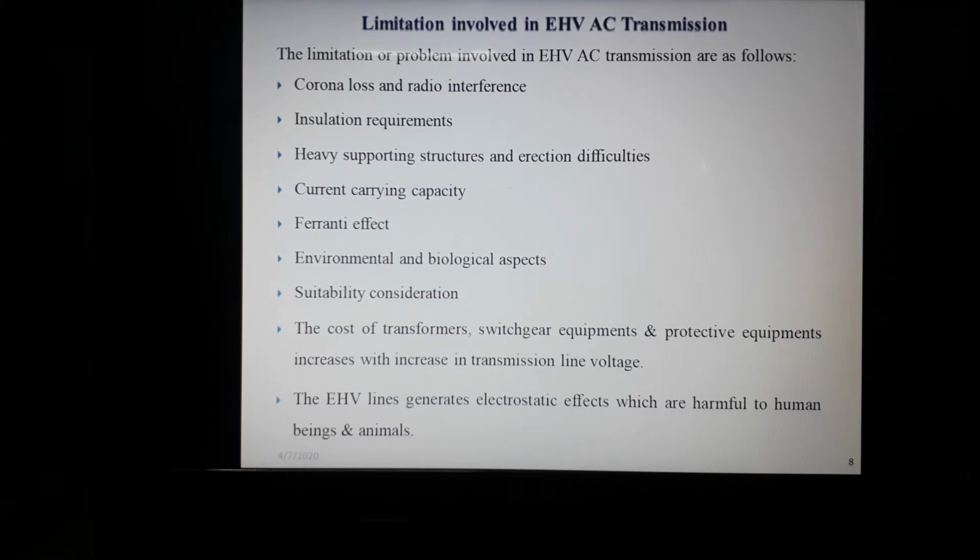So larger space between conductors, and between the supporting structure and conductor, is required in EHV AC transmission, and this produces heavy supporting structures for the power transmission, and also includes erection difficulties of these heavy supporting structures. The current carrying capacity is reduced as the voltage level is increased, and the Ferranti effect.